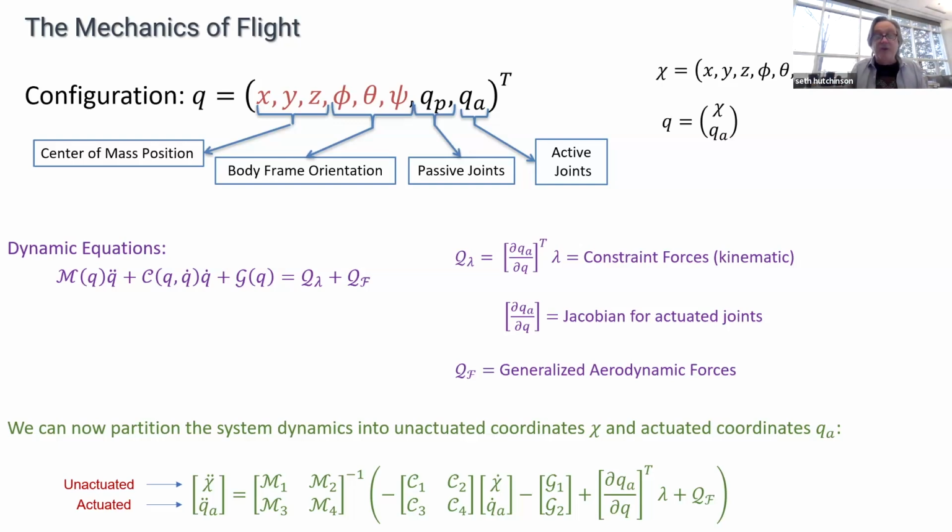And those are the things in this psi set of equations at the top. The actuated dynamics at the bottom actually are the bread and butter for roboticists, and we know how to use those. This is the tricky part, right? There are aerodynamic forces that happen here, and the aerodynamic forces are not friendly in any way. If you take away the aerodynamic forces, you're left with the usual Euler-Lagrange equations.